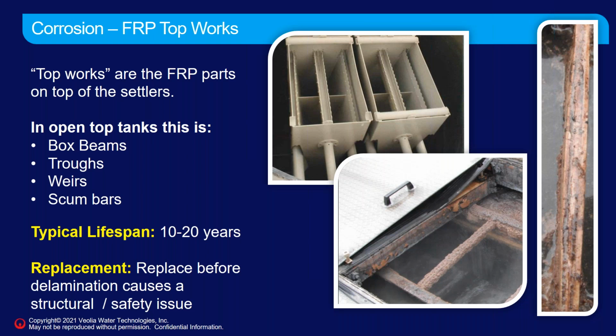So this stuff is mostly submerged under the water, but there are parts of it that are sticking above the water level, and that water level is slightly corrosive because you still have some dissolved H2S, CO2 in that water that's coming out of solution, mixing with the atmospheric air and causing acidic type conditions. That fiberglass is the best type of component up there, but it still has some lifespan. So typically it's 10 to 20 years.